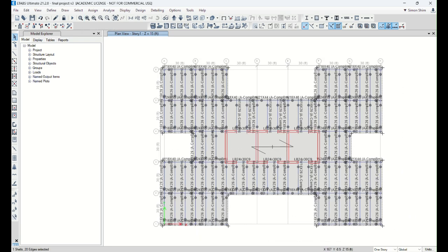So this floor, we just checked. I'm just giving the overall geometry, okay? First column and beam and girder and wall, you draw all of this. Again, just think about it. It's going to be the same procedure no matter which project you're working on, right? You need to define the geometry, the structural form geometry, but it's all coordinated with the architect. Set up the 30 feet spacing, right? That is very meaningful. It's not just random. This is the office module.